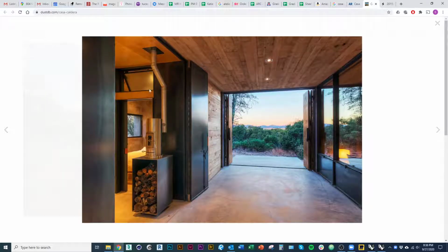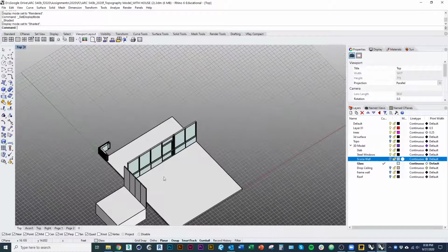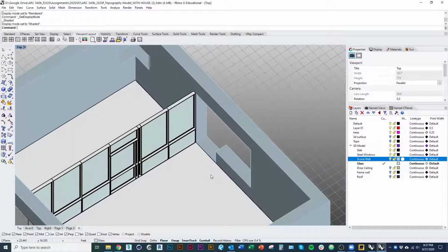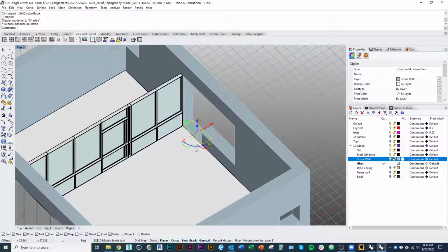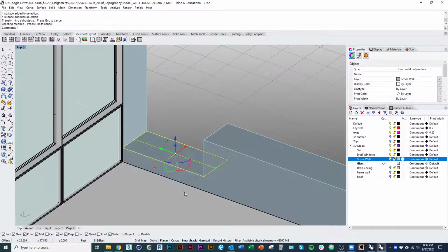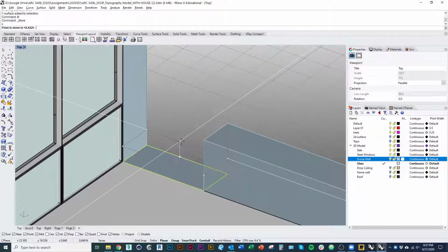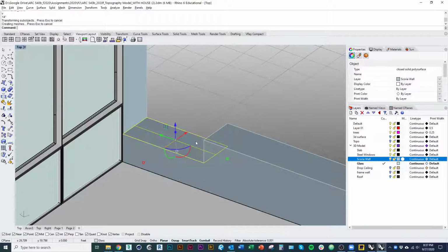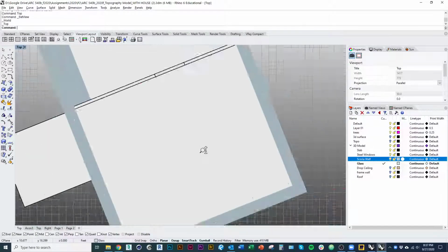So I would model all this stuff, like I'd model the framing of that, not the individual panels, but model them as a surface. I'm going to model this step. Do that. Okay. I guess I messed that up. Again, I can use Control Shift and select that surface, move it up. So it's 2 steps, so we'll move it up 14 inches. Like so. Okay. So I'll go to top view here.